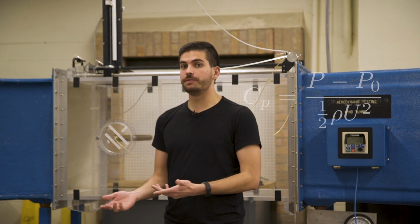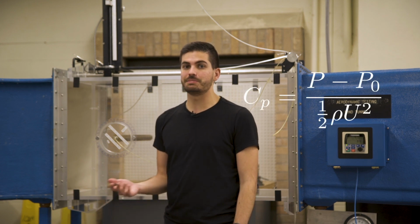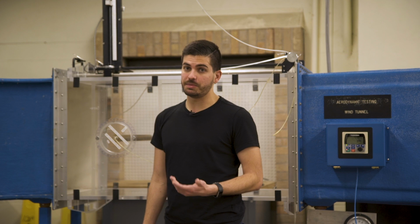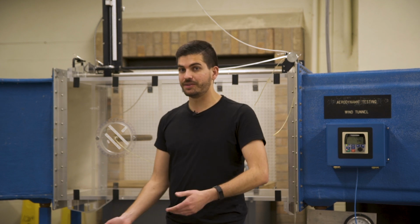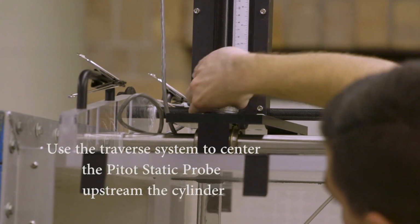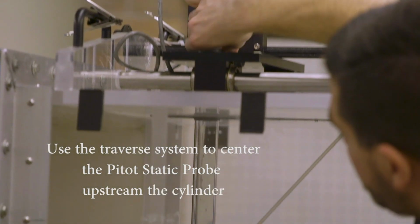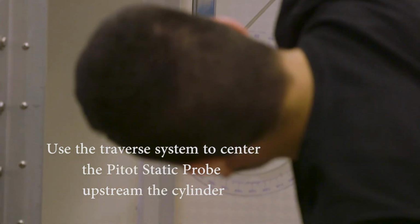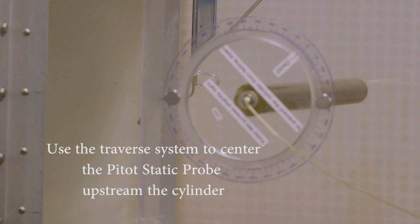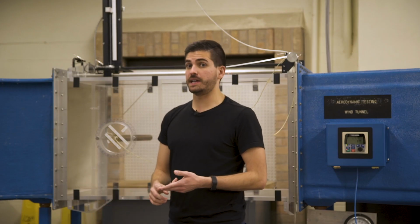These upstream conditions will also be useful when we're calculating our coefficient of pressure, which is a non-dimensional way to represent the pressure distribution around the cylinder. Much like the coefficient of drag, which is another non-dimensional number, this will allow us to compare our experimental results to those in the literature or from other laboratories. And you can do that using this traverse system, like such. We'll line it up, centered with the cylinder upstream. With this, we can know our upstream dynamic pressure and static pressure.